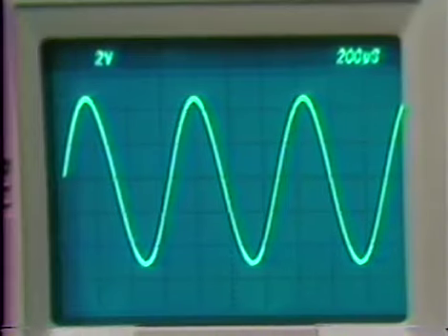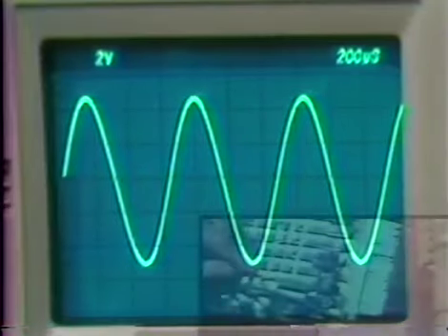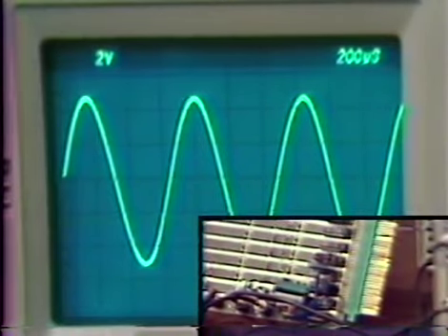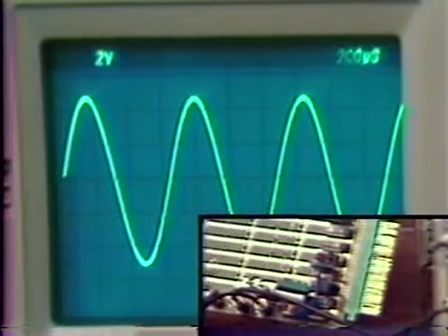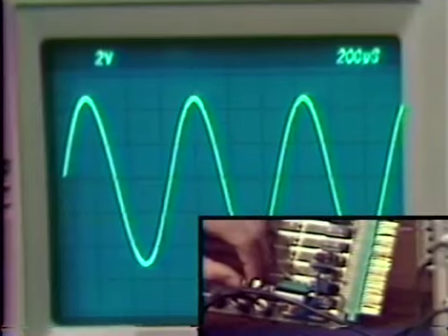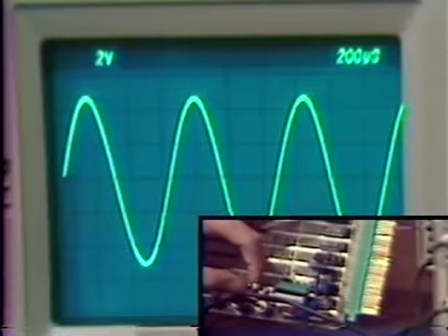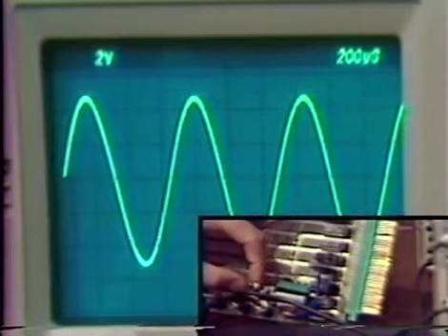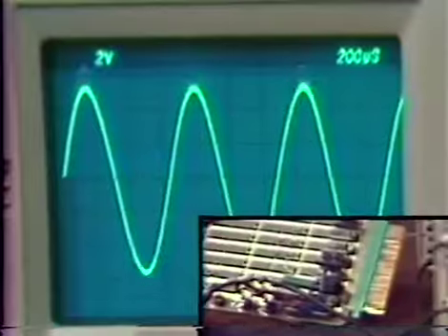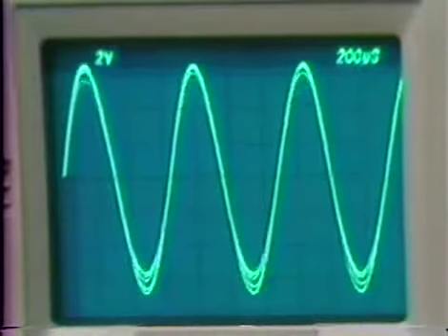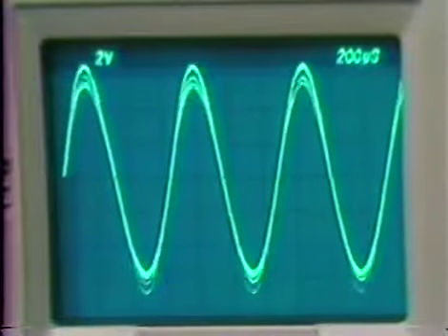What we're now able to do is change the switch that connects us from an internal reference for that amplitude, which is now about 5 volts peak or 10 volts peak to peak, to an externally commanded reference, and we'll put a square wave in as the command. So let's simply throw this to the other position. Now we see the modulation. We're again modulating at around about the same amplitude as we had before.